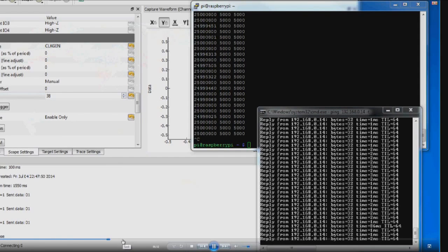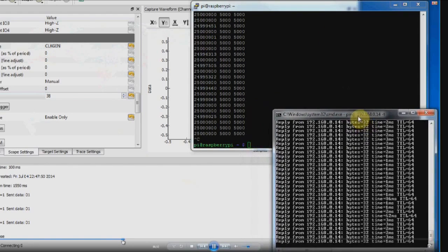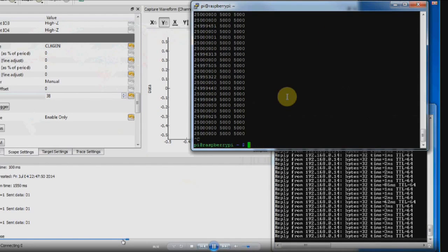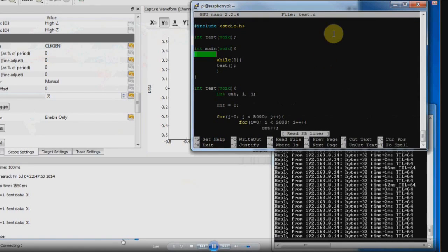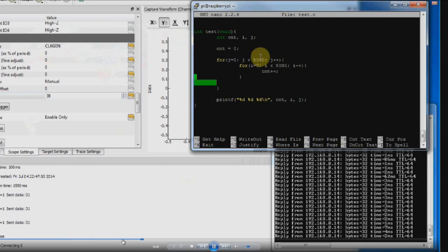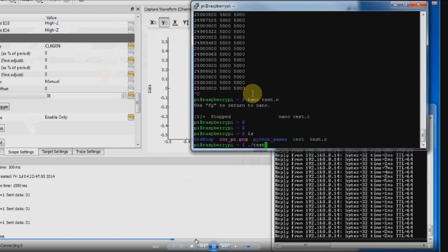And I have that same setup. I showed you the MOSFET, and it's connected to, in this case, a ChipWhisperer device to generate that pulse. You can, in fact, use a pulse generator or program an Arduino to set an I/O pin low and high for a certain amount of time. It's all about generating just that controlled short on the power rail. And again, this is the C code I'm using.